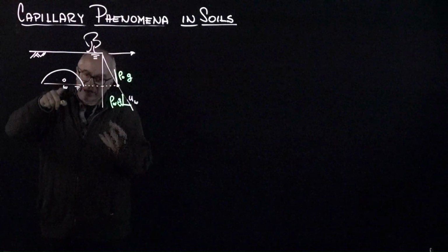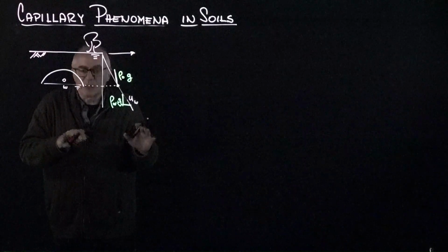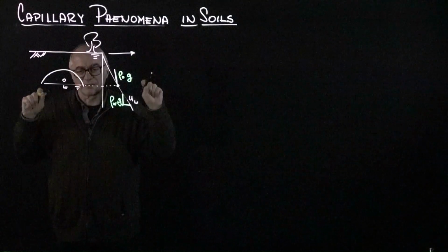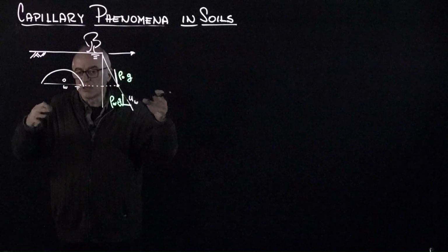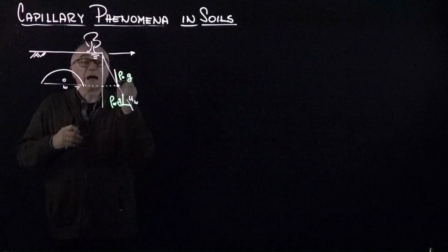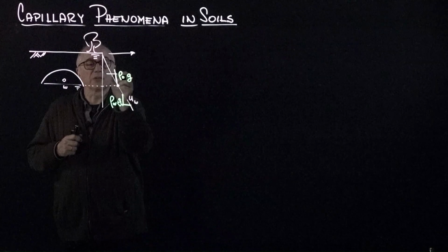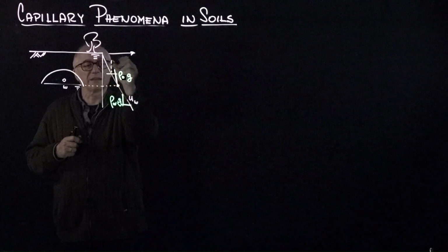The oil invaded and displaced the water, but the displacement was proportional to the soil-water characteristic curve, this capillary saturation curve. Now, at every point, I can compute the difference in pressure between oil and water, which is this quantity here.